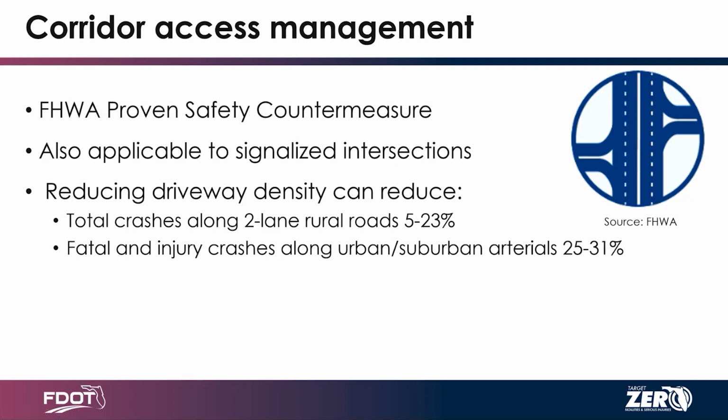Driveways can be in some ways, I hesitate to say this, a safety feature with really low speeds, in the sense that you're creating friction. So just keep in mind it's dependent. If you're 45 miles an hour plus, reduction of driveways is almost always a good idea. Once you start getting into different contexts, it starts changing.